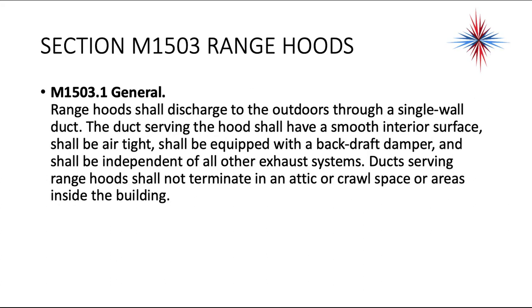Range hoods also have some specific requirements. Okay, this is kitchen range hoods. Now these requirements are important again because of grease and fire hazards that can contain grease. Range hoods should discharge to the outside through a single wall duct. The duct serving the hood shall have a smooth interior surface, be airtight, and should have a backdraft damper and shall be independent of all other exhaust systems. Ducts serving range hoods shall not terminate into an attic or crawl space or areas inside the building. Again, grease is a real fire hazard.